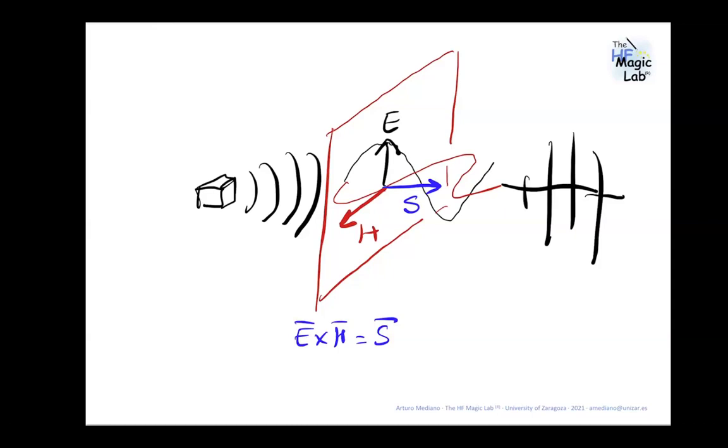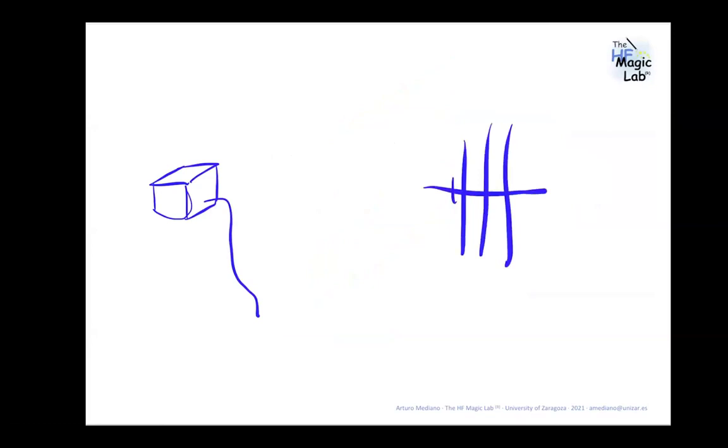This is going back to an earlier one, if we can keep them all straight. To clarify the earlier question: if I have good results in the horizontal antenna orientation, but bad results in the vertical orientation for radiated emissions, what would be the steps to move in between? Okay. Well, this is very difficult to answer, but let me consider that your product is a box like this one, and you have a cable, power, data, or something like that. And like you say here, you are failing in vertical polarization, not in horizontal.